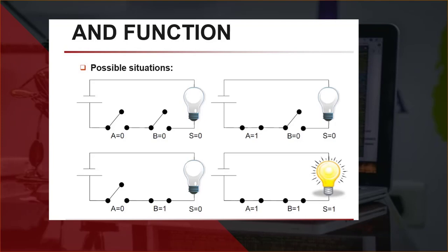Example of an electrical circuit in series, performing the AND function. The open switches represent logic level 0, the closed switches represent logic level 1, and the lamp is the response of this circuit. The lamp will only light up when both buttons are pressed, closing the circuit.